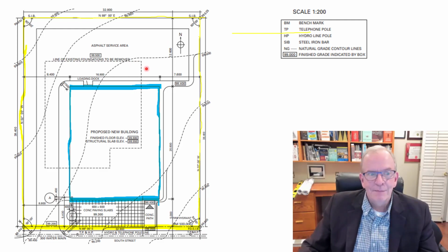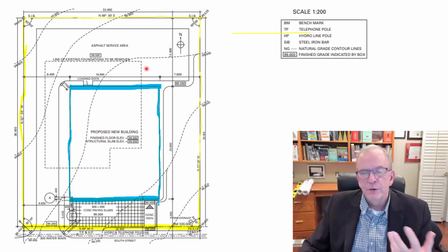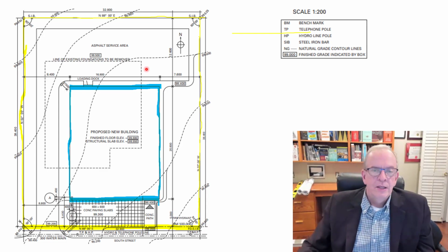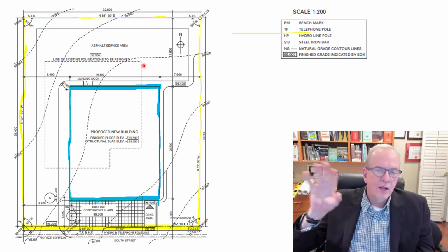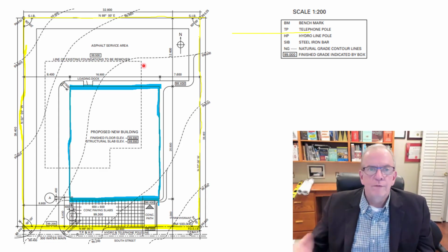So this is the map, it may not be exactly the way the map shows on site. So you always want to verify things, review it and check it on site. That's why usually in the title block, it'll be telling you to verify dimensions and check with the consultants if there's any discrepancies, because there are discrepancies. The map is never exactly like the territory, but it's usually pretty good.